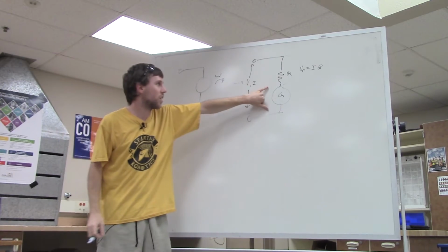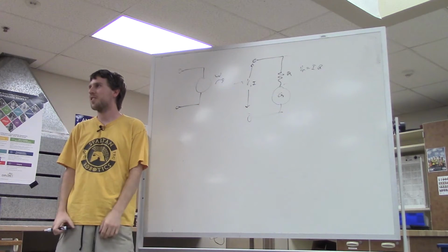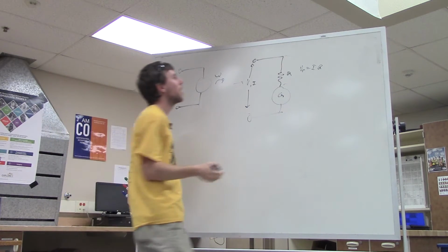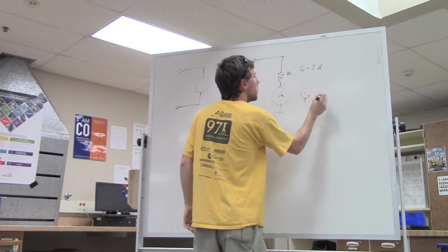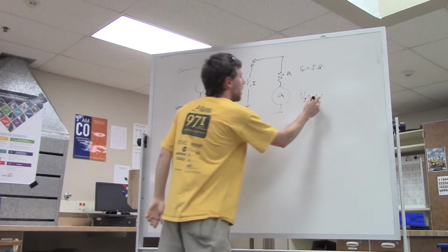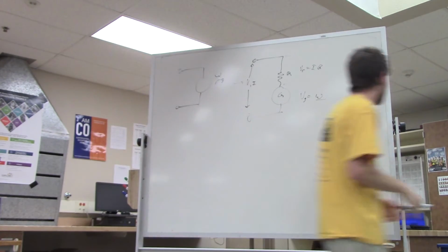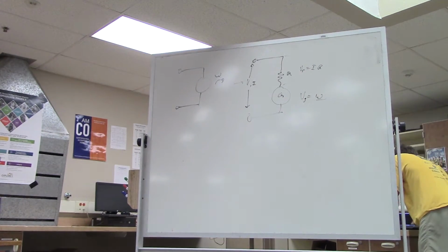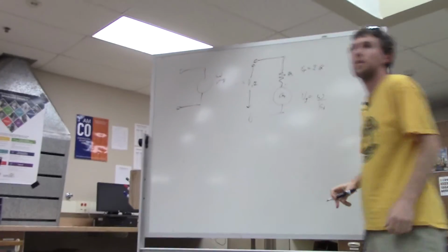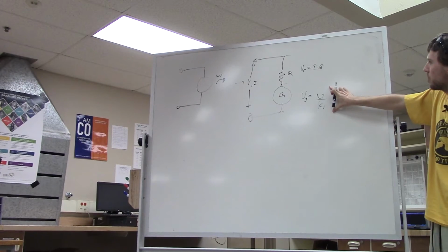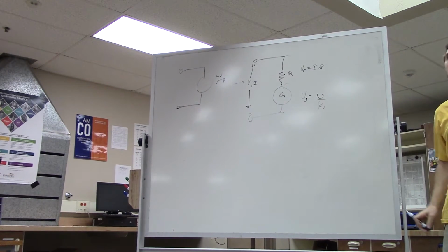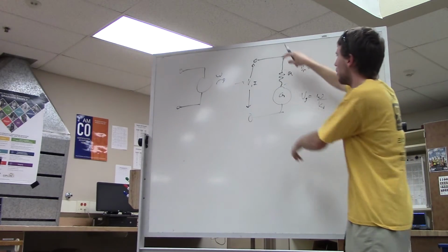So then this is a generator. The equation for a generator is the voltage drop across the generator equals the angular velocity times some constant. We'll use omega for the angular velocity symbol. And then, let me go check so I give you the right numbers, it's over kV. So the voltage drop across the generator is your angular velocity divided by your voltage constant. So we can add these together.